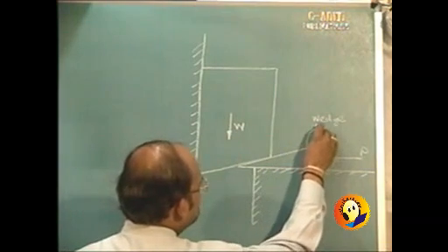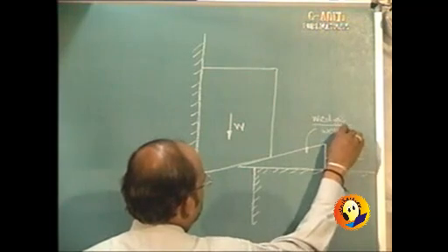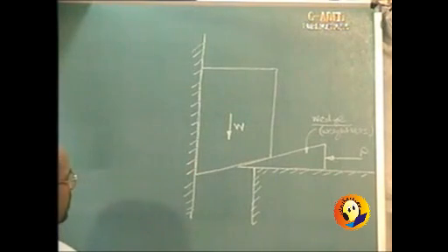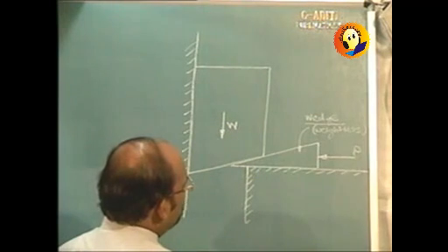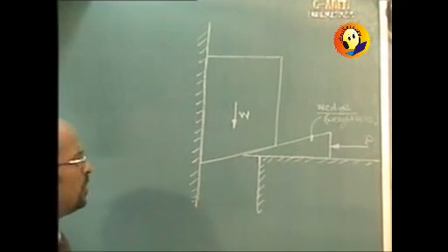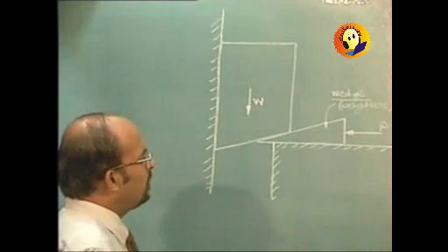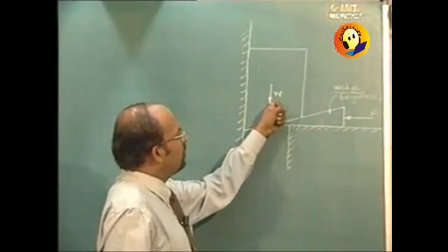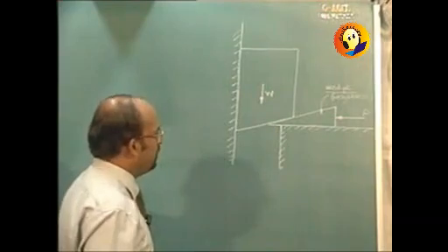Now this is the consideration. So far as wedge is concerned, it is normally considered as weightless. So in many applications you will find that the weight of the wedge is not given to us. But we also know that the frictional force which is going to come into picture is going to be proportionate to the normal reaction, and the normal reaction in this case will be dependent on the weight. But it is not the weight of the wedge which will be important, but the weight of the block is quite considerable, and weight of the wedge could be considered as the negligible one.